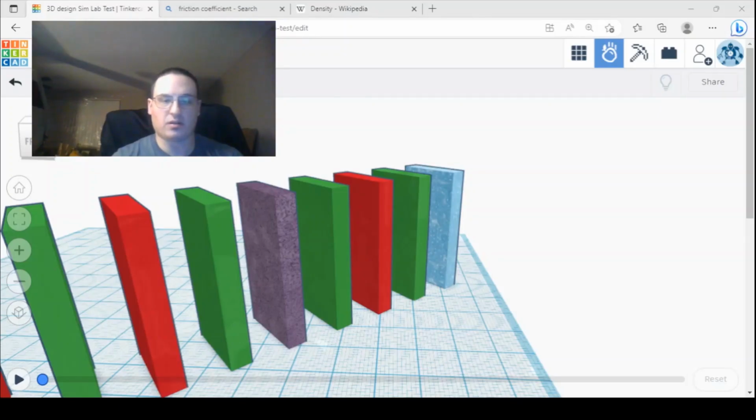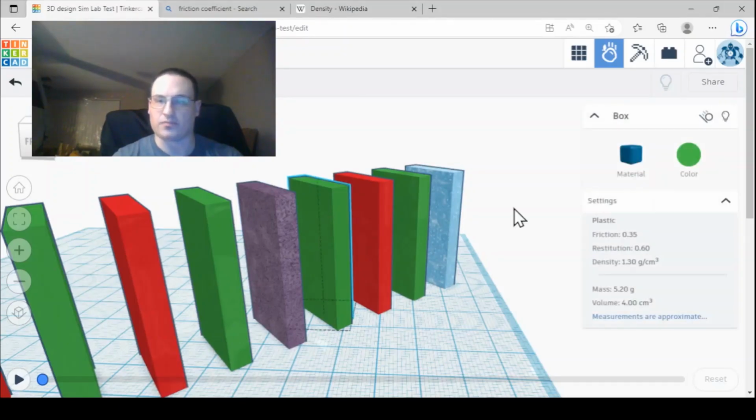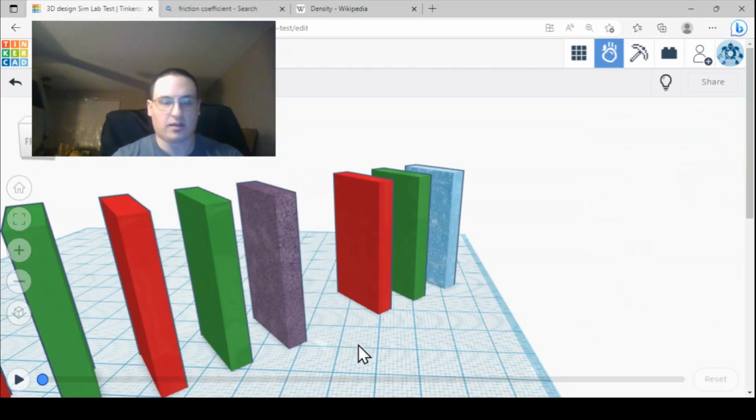So a nice feature also is, on this menu, you can make a thing static, or next to it, you could also hide it. So I click on that and hide that green cube. This could come in handy for a couple different reasons. If you're not sure how that part's going to look or work, you could take it out temporarily. Instead of deleting it and trying to put it back in, you could just hide it.